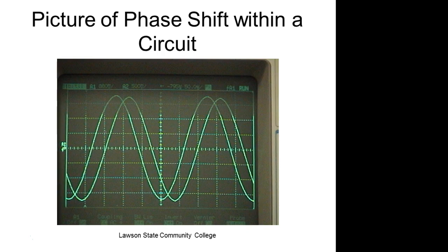So the power grid is predominantly inductive. So it tries to create a phase shift, what we call a lagging power factor. Capacitors like to create what we call a leading power factor, so capacitors and inductors cancel each other out. This is why every once in a while you'll be driving along and you'll see a power pole with three little square boxes on it.